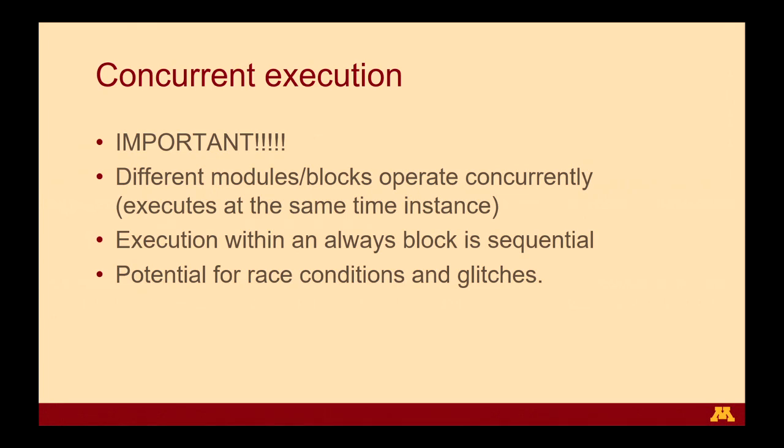The way to look at Verilog code is that each module is by itself a parallel thread, and every module executes in parallel. So you can never guarantee any sort of ordering between different modules